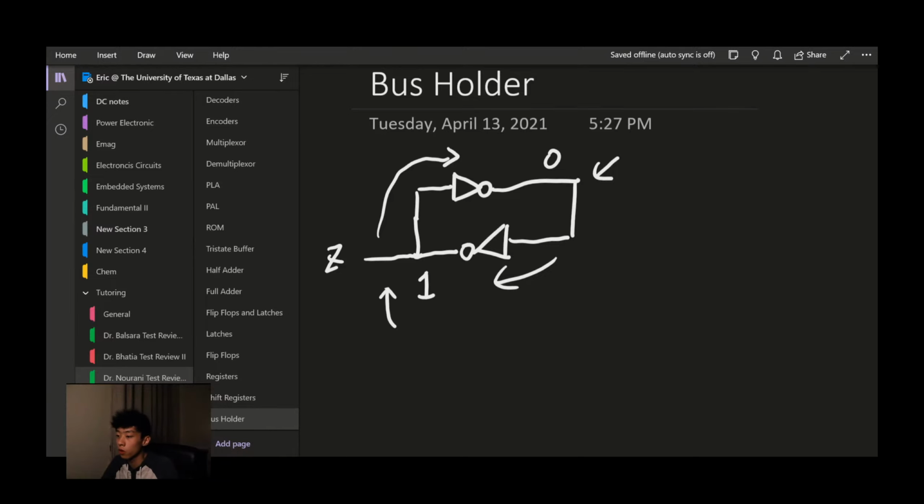The reason that we are using this instead of flip-flops is to reduce the area size of a silicon wafer. Flip-flops use more transistors than inverters, so using this will give us a more simplified version compared to the flip-flop.